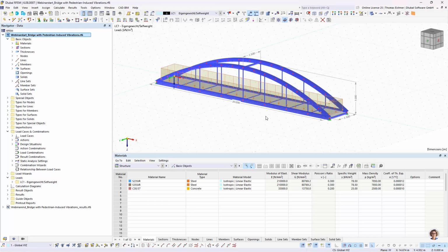Now we could also think about giving it a snow load on top, right? But it would change the dynamic behavior of the structure, since the masses are different in that case. But more than 3/4 of the year there wouldn't be snow, so it's not really a good approach in this case. So we're going with these masses here.